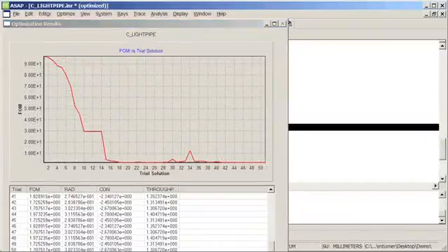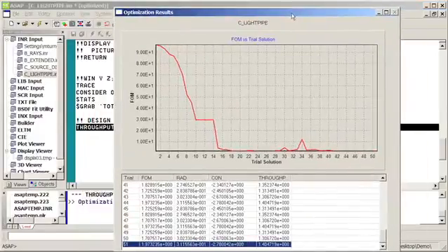And after ASAP has processed the requisite number of trials, the optimization will come to a halt. And as you can see, ASAP was able to find several solutions around a particular maximum coupling efficiency. And again, this is simply because there are a wide range of conic curves, combinations of radius and conic terms that would give us approximately the same solution. Again, we're going to save one of the solutions and just take a look at it.